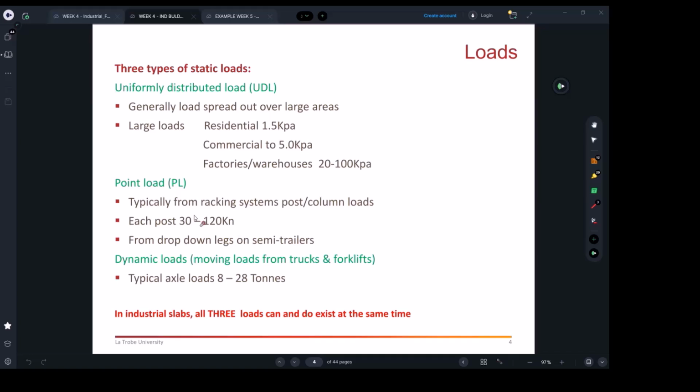When it stops, it's going to be pushing the ground harder because there's gravity and there's inertia, acceleration. So engineers will be calculating factors to amplify this. That factor may be 1.5, so we end up with 45 instead of 30. And again, that's why you can see we start talking about tons here. It's really heavy. Tons is heavier than kilogram.